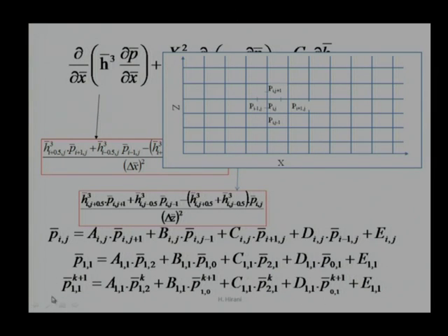That is going to decide our pressure term, while A, B, C, D, E will remain constant. They are not going to vary with iterations. So, iterations are only required for this purpose. And for simplicity, when we start the solution, we assume the pressure at all the nodes is equal to 0, and we can assume that as k equal to 0, the 0th iteration.